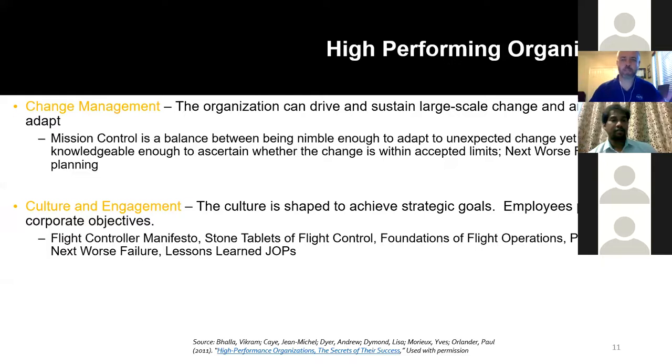So a quick example, the space station has 2 primary cooling loops outside of the space station. You cannot connect the 2 together, and each of them has a single pump that is running continuously. If one pump fails, you lose half your ability to get the heat removed from the space station. And rejecting heat is a big thing that you always have to do with your spacecraft. So we have procedures to respond to a failure of a pump. It's pretty straightforward. It's a pretty simple task. It takes a couple days to respond to. But we don't stop there.